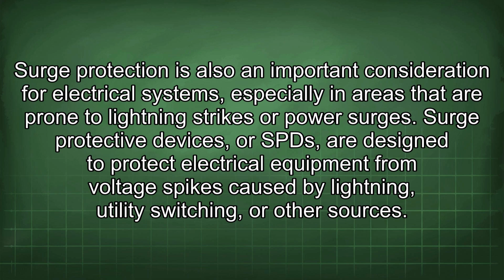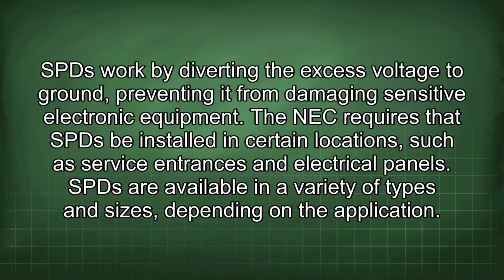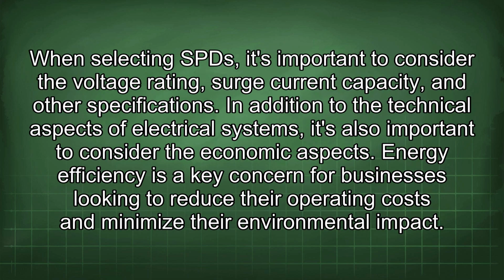Surge protective devices, or SPDs, are designed to protect electrical equipment from voltage spikes caused by lightning, utility switching, or other sources. SPDs work by diverting the excess voltage to ground, preventing it from damaging sensitive electronic equipment. The NEC requires that SPDs be installed in certain locations, such as service entrances and electrical panels. SPDs are available in a variety of types and sizes, depending on the application. When selecting SPDs, it's important to consider the voltage rating, surge current capacity, and other specifications.